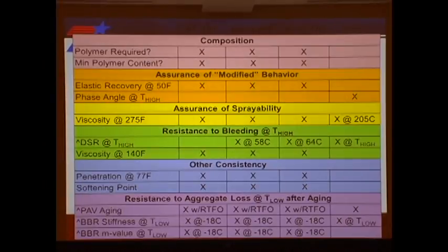Down in the purple, we're talking about the low temperature properties. Now the old-fashioned AC spec would not have anything in there because we didn't run any low temperature tests. Over time, we had some PG properties that crept in there, which kind of represents SPG sneaking into things in an early sense from way back. But we would run a DSR, we'd run a BBR test, which is designed to identify cracking in hot mix, and we would use that to make sure we had good low temperatures for that binder. Well, we're still doing that, and we're adding that in some cases for SPG binders.